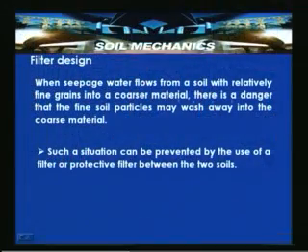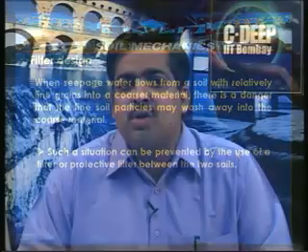Being synthetic in nature, they have a long life and enhanced performance compared to conventional filters. So, when seepage water flows from a relatively fine-grained soil to a coarser material, there is a danger that fine soil particles may wash away into the coarser material, and such situations can be prevented by use of a filter.